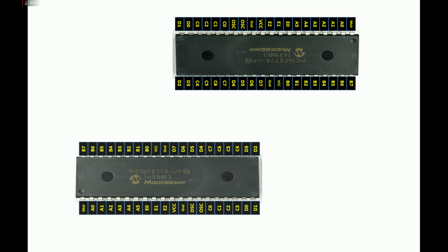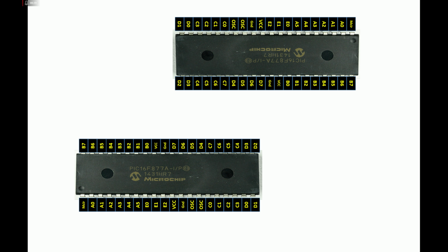That's very simple. So guys, this over here is our first PIC, PIC16F877A having 40 pins. It's a DIP version. This is the second PIC, PIC16F877A, a DIP version. Then let's do the connection. Since we are using a UART port, pin number C6, that is pin number 25 of the one PIC, is the TX pin, while pin number 26 of the PIC, that is pin C7, is the RX pin.